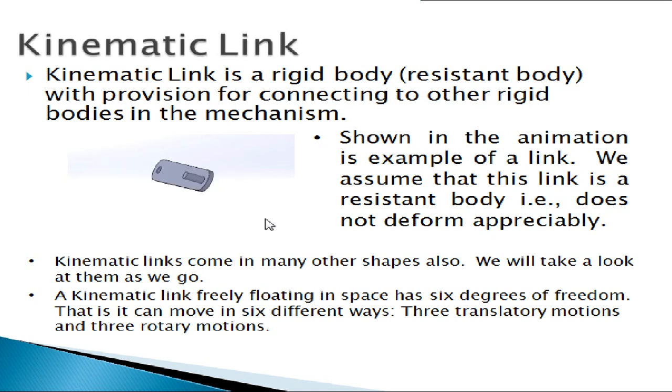So it has a thickness, it has a pin, it has a hole. This link as shown here is shown to be floating in air. Such links which can move in all directions are said to have 6 degrees of freedom.